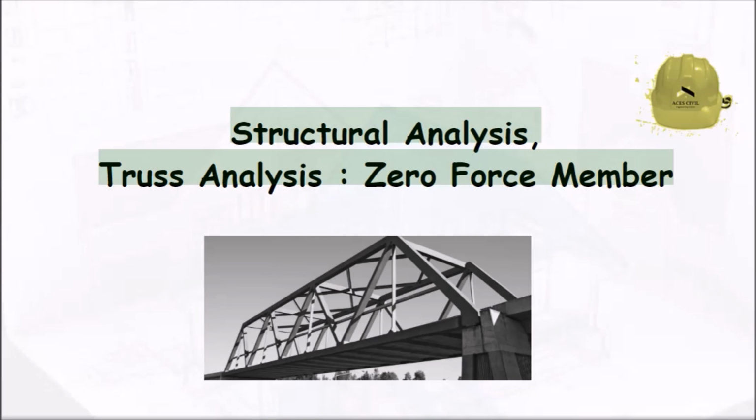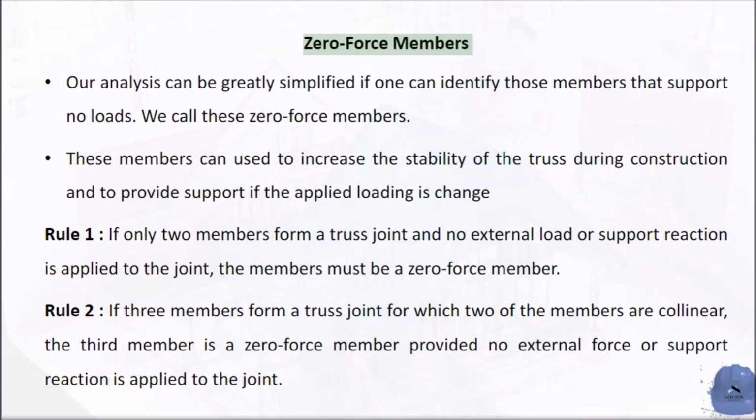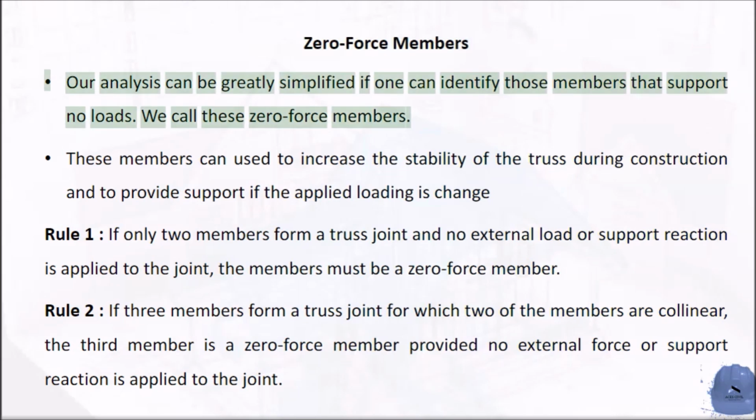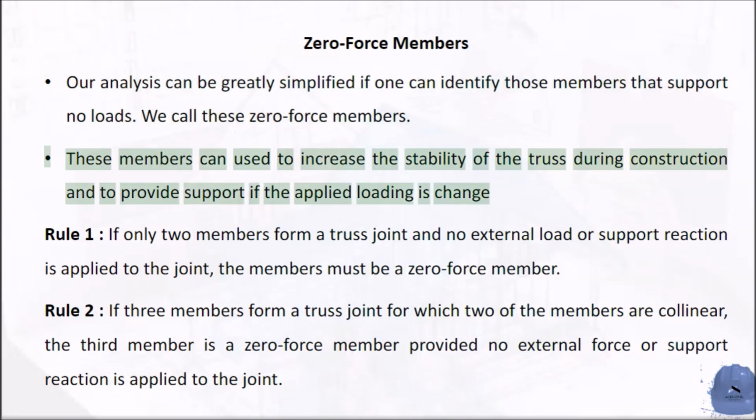Structural analysis, truss analysis, zero force members. Our analysis can be greatly simplified if one can identify those members that support no loads. We call these zero force members. These members can be used to increase the stability of the truss during construction and to provide support if the applied loading is changed.